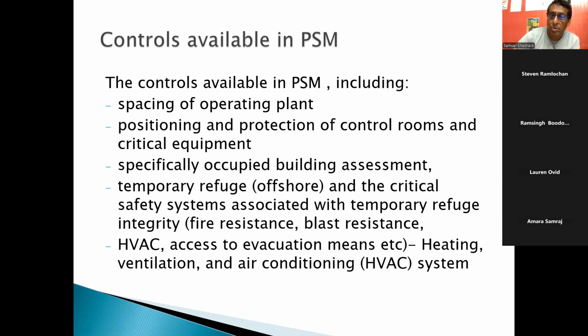For those who do know, a refuge room, which is a place you go in the event of a fire and explosion, is meant to withstand a fire for a certain amount of time. They can actually calculate that, like 30 minutes, 20 minutes, etc. There are certain things you can put on the door, like intumescent materials and fire retardants, meant to give a certain amount of integrity. They call it stability over integrity. There's a formula for it.